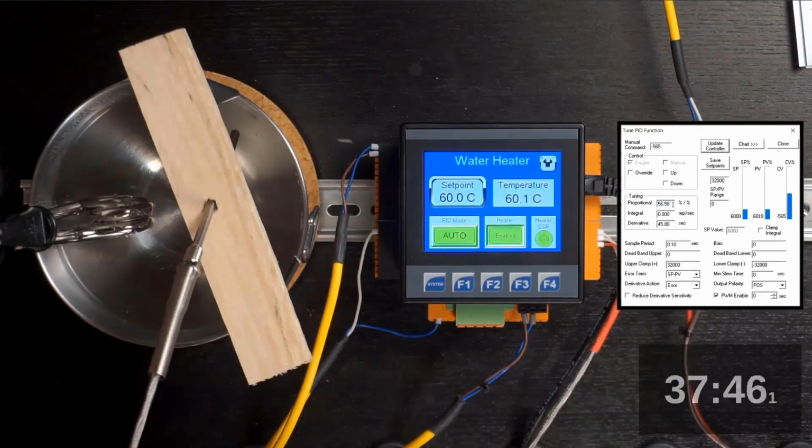The most important thing about this video is the process that you go through when tuning a PID loop, where you're starting with an auto-tune, getting through the auto-tune, getting to the point where you're making manual adjustments, checking to see how those are doing, and then taking it from there until you're satisfied with the results.